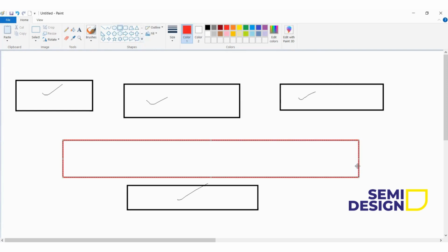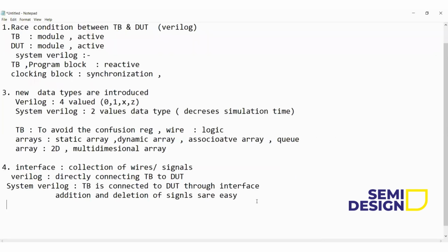Now there is this interface. So how do I connect the signals? Let's say an adder, M1. Here dot input, then dot input 2, then dot out. So here these are my module signals and these are my test bench signals. So I have connected like this.